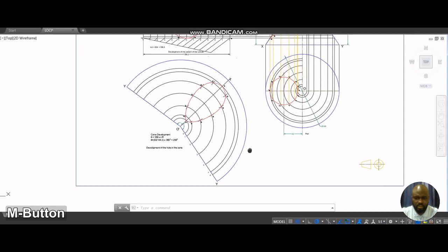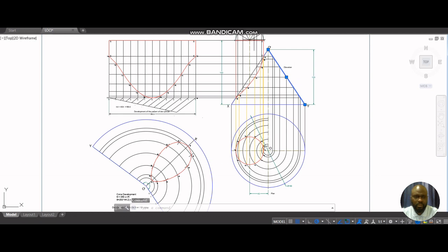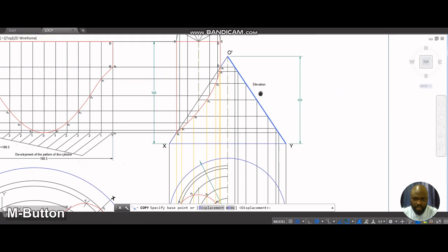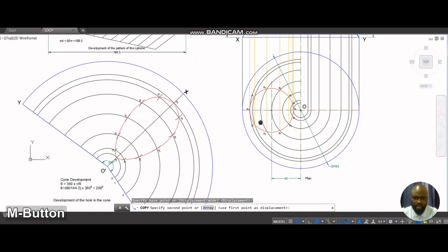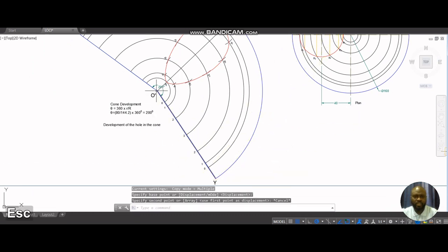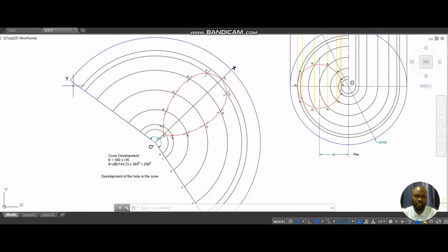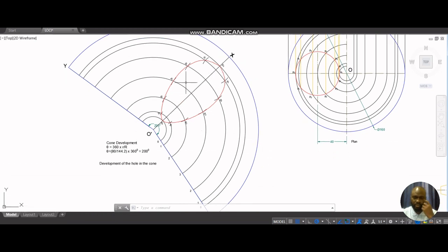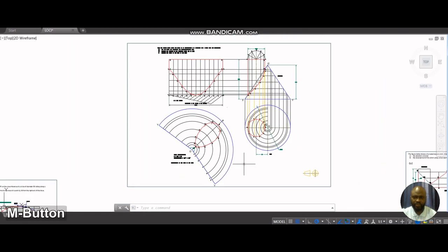But of course, if you're using a compass, physical instrument, so to speak, all you need to do is to set your t-square and your set square to copy this line. Copying of lines is a skill in technical drawing. Copy this line at this angle, and then transfer it down here. Now with center 0, draw all the arcs the way you drew them before, and then you will still achieve the same result as we did. Other than that, nothing is different in what we have done.